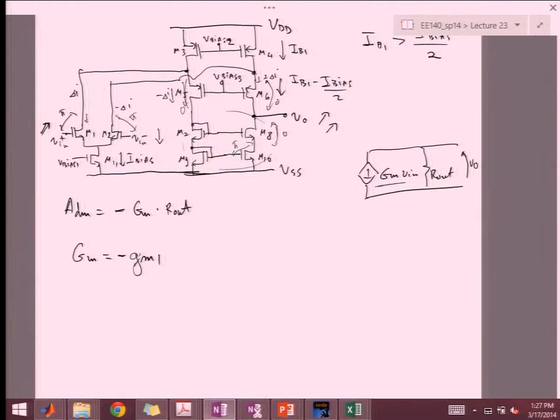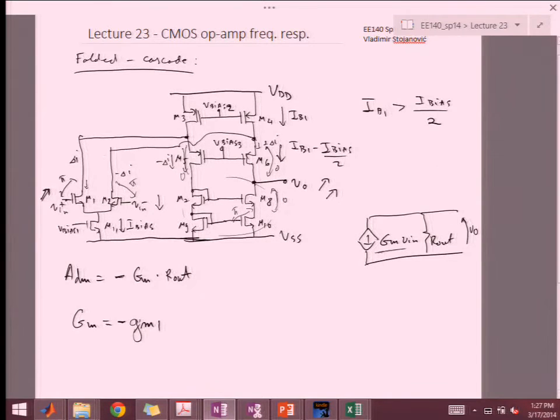People understand this? So this is the useful way of quickly analyzing the amplifier, right? You go by the functionality of what we intended these different pieces to do. Remember, when we did folded cascode, I first drew this piece over here as just a current mirror. That's the general functionality. A current mirror will just move whatever changes on the input to the output in current. So it's really not doing transconducting. It's not moving voltage into current. The only piece that moves voltage into current is this input diff pair. Therefore, the whole transconductance of the circuit is based there.